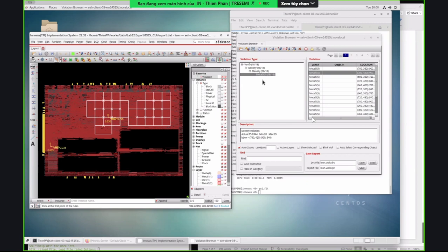Yeah, that's very true as you go to lower geometry like 3 nanometers, 4 nanometers, because at lower geometry, wire dominates, right? What we normally do on a design is close timing without metal fill, and then when we do metal fill, you see timing degrade, meaning it got worse. Then we have to go back and do incremental timing fixes again. So it's a loop process. Yep, metal fill has great impact at lower geometry in terms of timing closure.